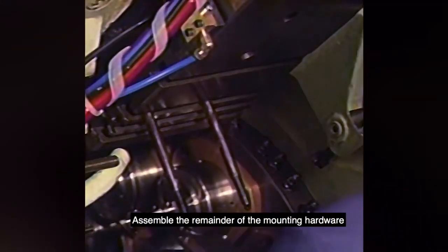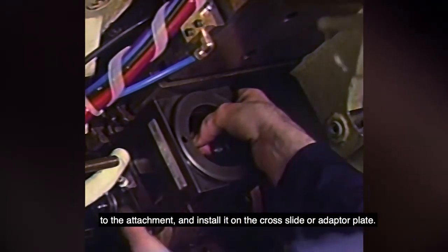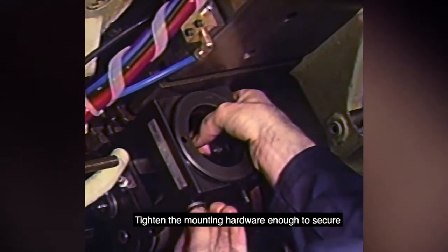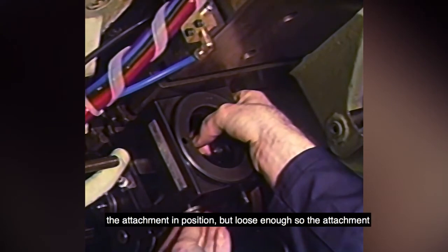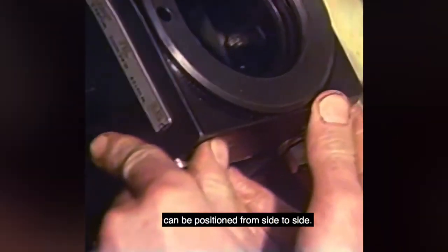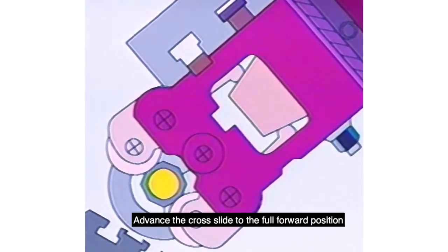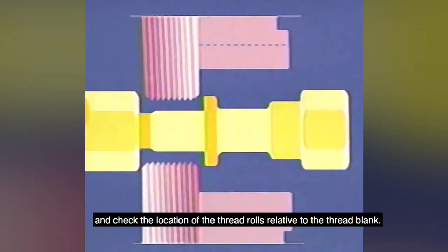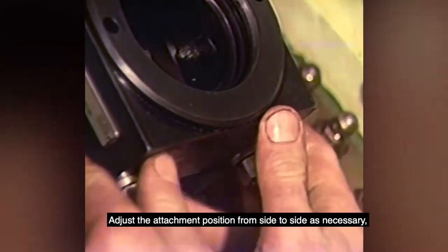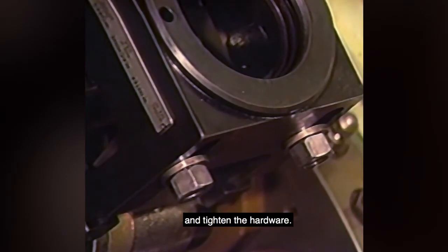Assemble the remainder of the mounting hardware to the attachment and install it on the cross-slide or adapter plate. Tighten the mounting hardware enough to secure the attachment in position, but loose enough so the attachment can be positioned from side to side. Advance the cross-slide to the full forward position and check the location of the thread rolls relative to the thread blank. Adjust the attachment position from side to side as necessary and tighten the hardware.